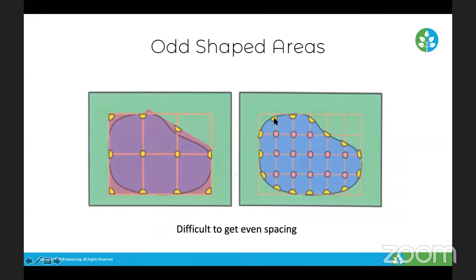So this is when spacing and grouping, the idea is still going to be the same. The sprinklers need to be the same distance away from each other. That's how you would go with odd looking shapes. Still use the grid method and keep things evenly spaced so that we know which type of nozzles to put in, but just a rough grid spacing.